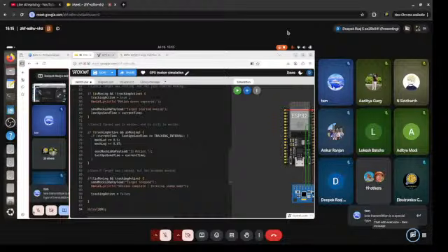Okay, here the Wire.begin just initializes the I2C protocol. It sets 21 to SDA and 22 to SCL. Compile takes some time. So after it compiles, I'll tell you what you will see.